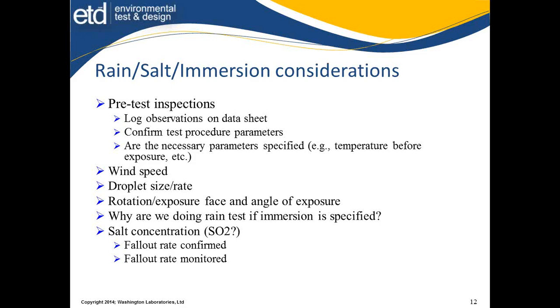Is it feasible for the salt fog fallout to be checked, written down, and nobody sees whether it's right or not? So we go on, and after 14 days of exposure, we realize that on day 3 and 4 it wasn't working right. Does that invalidate all the tests or just days 3 and 4? Out of a 14-day test, I've lost my days to be correct.